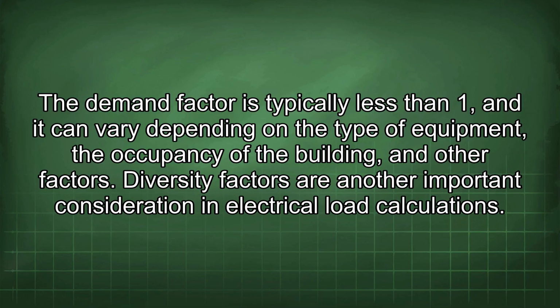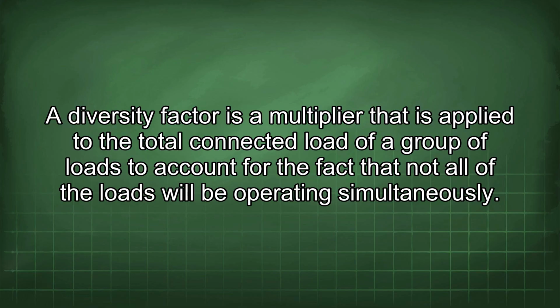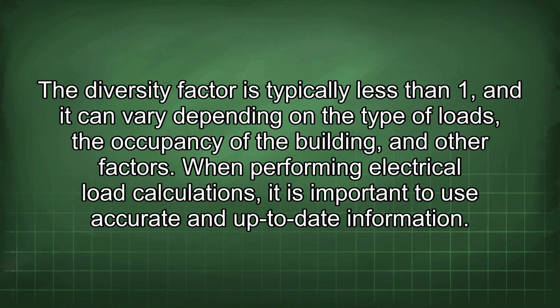Diversity factors are another important consideration in electrical load calculations. A diversity factor is a multiplier that is applied to the total connected load of a group of loads to account for the fact that not all of the loads will be operating simultaneously. The diversity factor is typically less than 1, and it can vary depending on the type of loads, the occupancy of the building, and other factors.